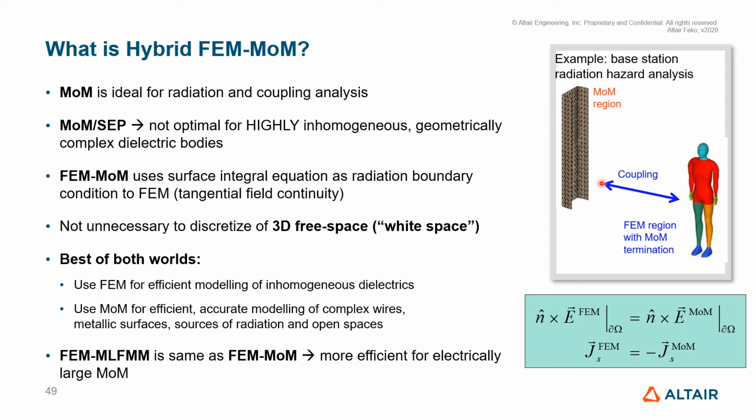Of course, the base station antenna, which is a metallic structure, can be modeled with method of moments or MLFMM, and the coupling between these two is taken into account. So it doesn't matter whether it's 10 meters, 15 meters, 30 meters, 50 or 100 meters. We have the same computational requirement as having the whole space discretized. So this gives you the best of both worlds.